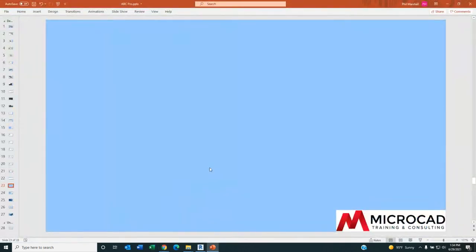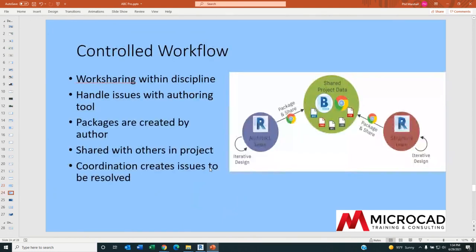All right, so it showed you within the Revit family and within the Autodesk Construction Cloud environment how the information is shared from person to person. Let's refresh our memory on what the workflow is, because this is the sort of thing that you would be able to configure by each project. Within each discipline, the architect, the MEP, the structure, fire protection, they're using Worksharing within the discipline to have multiple people work and synchronizing to a central file that lives on the cloud.